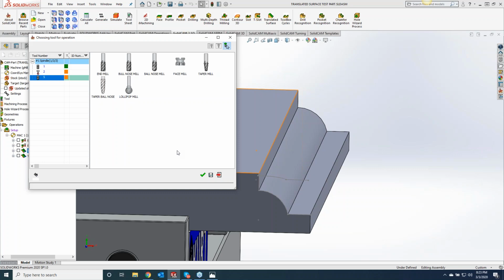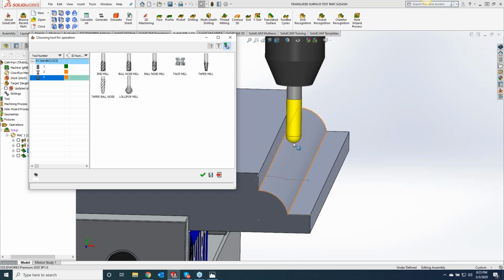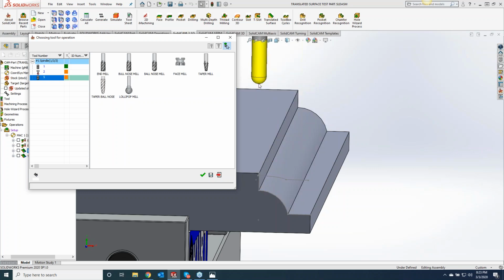So even on this particular one over here, we could hop in there with a high feed face mill and get that material removed out of there quite quickly. Great question. For anybody that's doing any kind of 3D roughing like this, and didn't have some of our more advanced features, this might be a good tool path for getting a near zero finish for a finishing tool path, but with the roughing style tool. Absolutely. Like I said, come back with a finisher and be set.